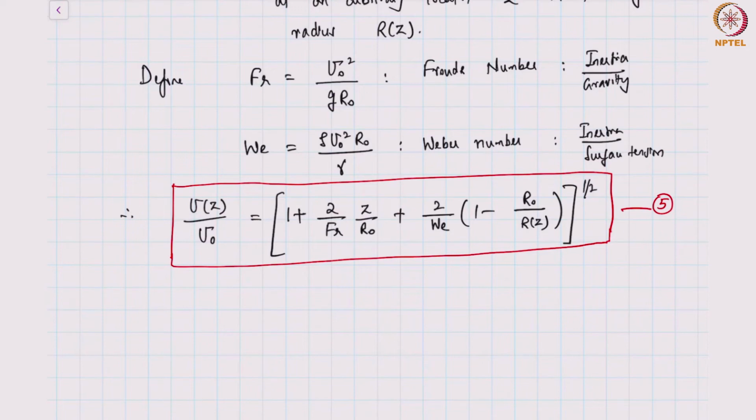So what have we not used? We have applied Bernoulli's equation, which comes from the mass, momentum, or the energy equation. We still haven't used one more important equation, which is the mass balance. Now we will apply the mass balance. It's a fairly straightforward relationship. It says that the mass flow rate coming at the inlet should be equal to the mass flow rate at the outlet for the control volume.